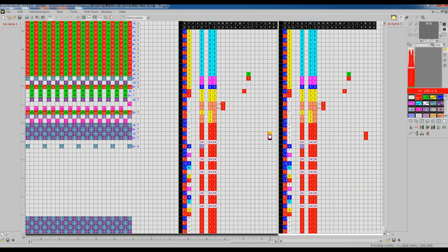After casting on, the ravel yarn interlock stitch courses are set to repeat 1. The number of repeats can be set on the knitting machine after importing the machine code. Different machines have different requirements on how many ravel yarn courses are needed. After ravel yarn knitting, the stitches are transferred to 1x1 ribs.